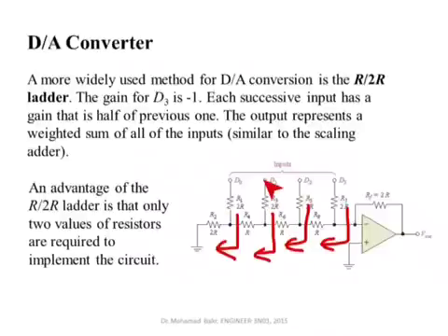If you make this one only high, so this one is logic 1, it is V reference, 9 volts or 5 volts, whatever, and all the other 3 digits are zeros, what's seen here is a voltage source of value Vref over 8. This one will give you Vref over 4, this one will give you Vref over 2, and so on. So they give you different weights depending on the position, and as a result the output increases with the binary count of these 4 digits.